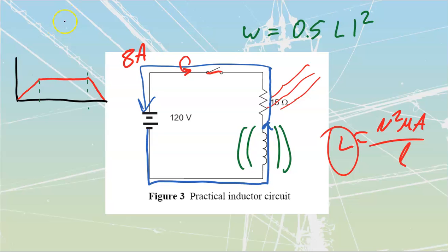And this was for a conductor that had current traveling into it like that. What we saw during the rise, and you can go back into the other video and verify it, is that we had a counter EMF that created a current that was opposing, coming towards us. We're going to indicate that with the dot. And during the falling current, when my current through the main conductor was falling, my counter EMF made some small currents that were going to try to aid this one over here, because they want to oppose any change in current. When the current was at that level, that's what the inductor dreamed of being able to keep it at, so it was collapsing lines of flux back in to try to maintain that. When this was rising, it tried to oppose that over there.